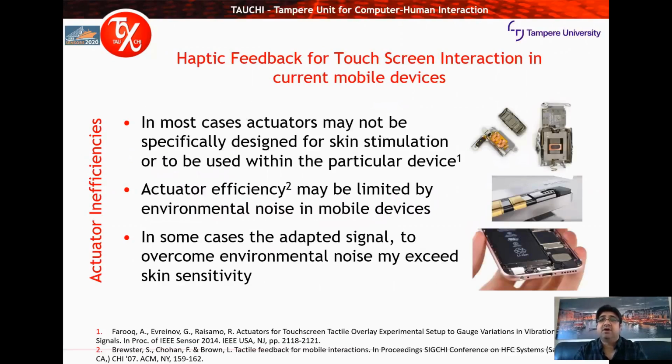Most actuators are also not designed to simulate the skin receptors directly. In fact, their limited mechanical efficiency dictates how generic haptic feedback signals should be created throughout the entire device. In a haptically noisy environment, certain frequencies may be unusable, which may render this type of global haptic feedback system inefficient or weak. To circumvent noisy environments, higher frequencies may be utilized, which can cause unwanted results, such as erroneous selections or parasitic vibrations.